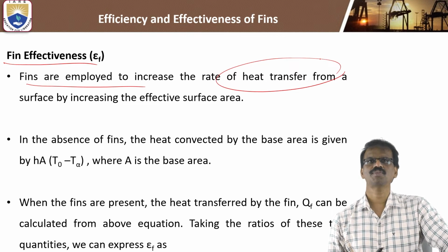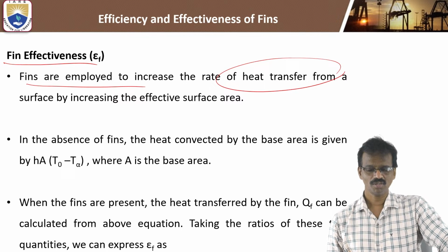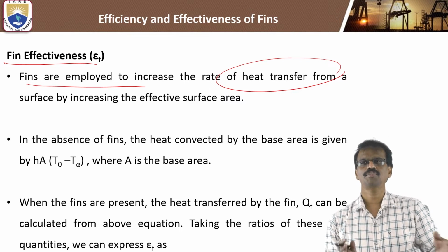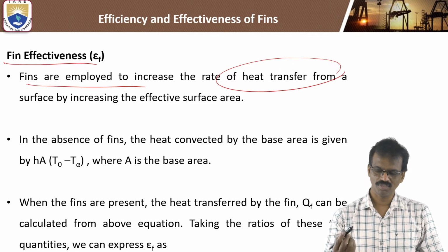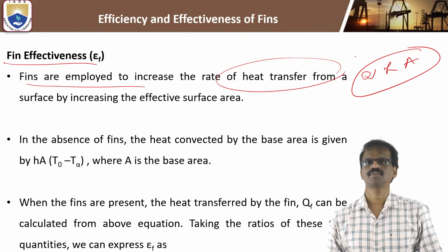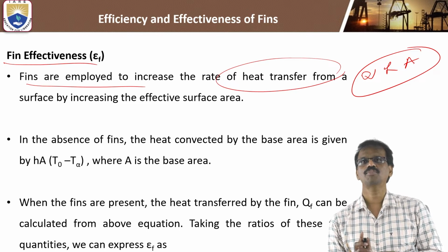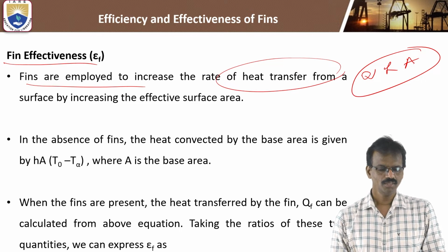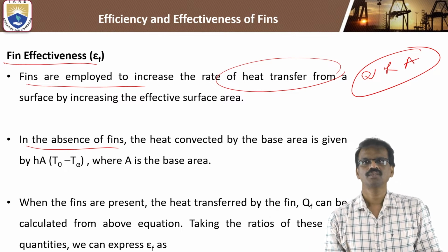The main object of the fin is to enhance the heat transfer rate. Because if you add the fin to the base surface, the effective area automatically increases. If the effective area increases, the rate of heat transfer automatically increases, because q is directly proportional to area. You know that. This is the main function, the intended purpose of the fin. So in the absence of the fins, if the fins are not attached,